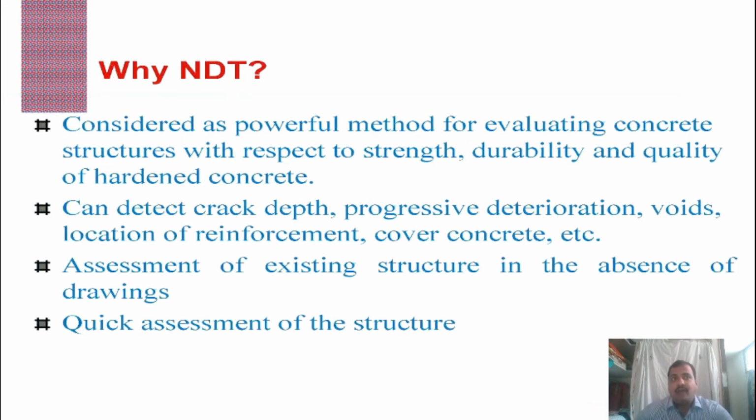Now, why do we use these NDT techniques? Basically, NDT techniques can be applied to both old and new structures. For new structures, the principal applications are likely to be for quality control or resolution of doubts about the quality of material or construction. The testing of existing structures is usually related to an assessment of structural integrity or adequacy.